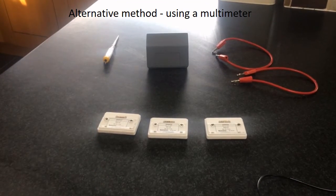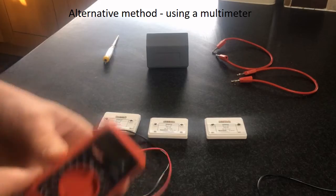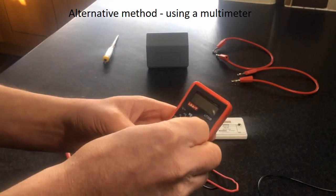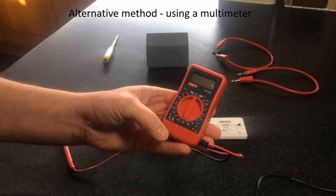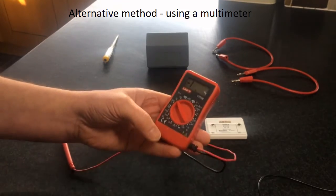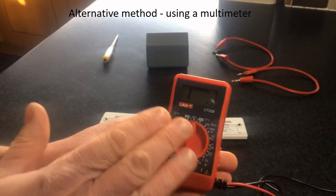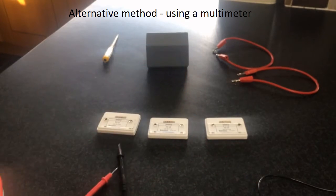Right, let's look at alternative methods. So the alternative method is not to use power pack, ammeter and voltmeter at all, it is to use one of these, which is a multimeter. A multimeter can be used for measuring potential difference, that's AC on that side, DC potential difference this side. It can be used for measuring current. This one won't do AC, it'll just do DC, and depending on where you put it, it will measure up to different amounts. If I slide that down to the bottom there, it will read up to 200 ohms. So now this is working as a resistance meter, an ohm meter, so it's measuring resistance directly.